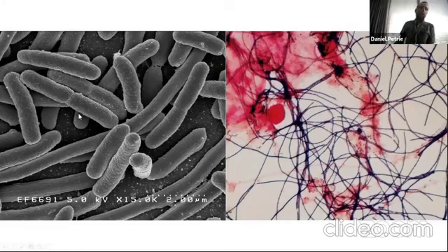But if you feed them food and you leave them for a really long time, then they start to compete with another class that are less dense and are more kind of filamentous. And these are commonly called filamentous bacteria. And they don't like to settle in a tank, so they're very hard to remove. But ultimately, how the biomass grows dictates how your sludge behaves and how it dewaters.